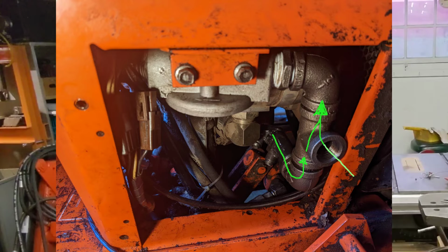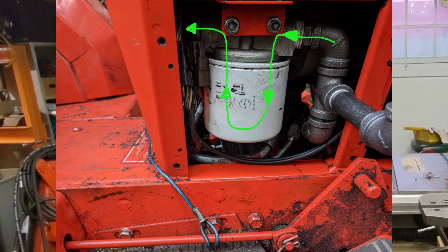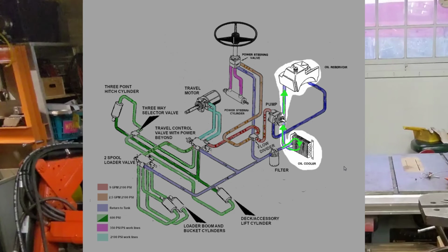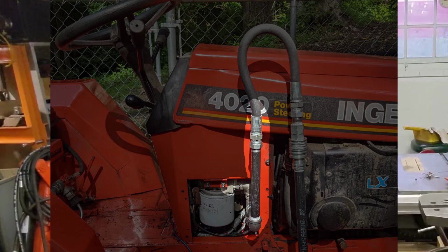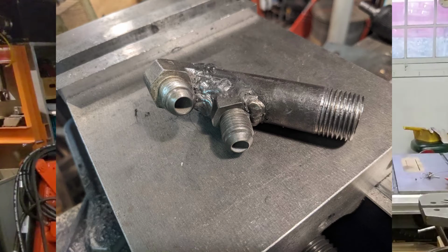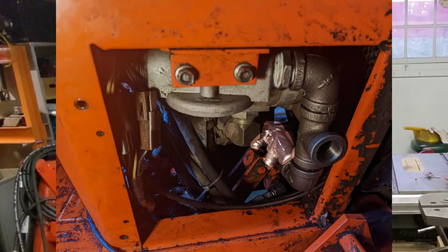All return oil will be routed into that manifold. From there, it'll pass through the oil filter and then through the oil cooler and then up into the fitting on the bottom side of the tank. The return-to-tank manifold consists of a regular half-inch NPT T that'll be connected to the new return side quick disconnect and a small pipe nipple onto which I've welded two JIC6 male stubs.